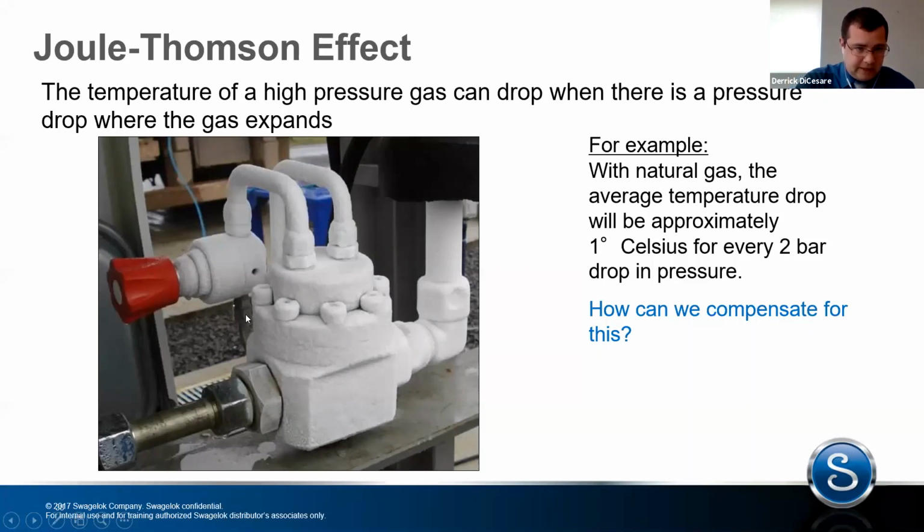You can even see the inlet side back here, which will show in a better picture a couple slides from now. The inlet to the pilot regulator is not iced up either. So as that pressure drops significantly, you can see icing on the outlet side.